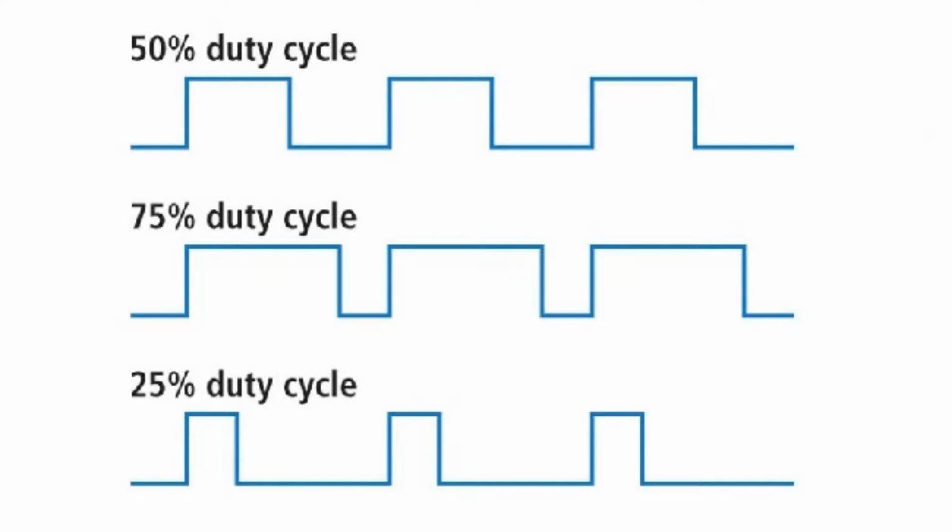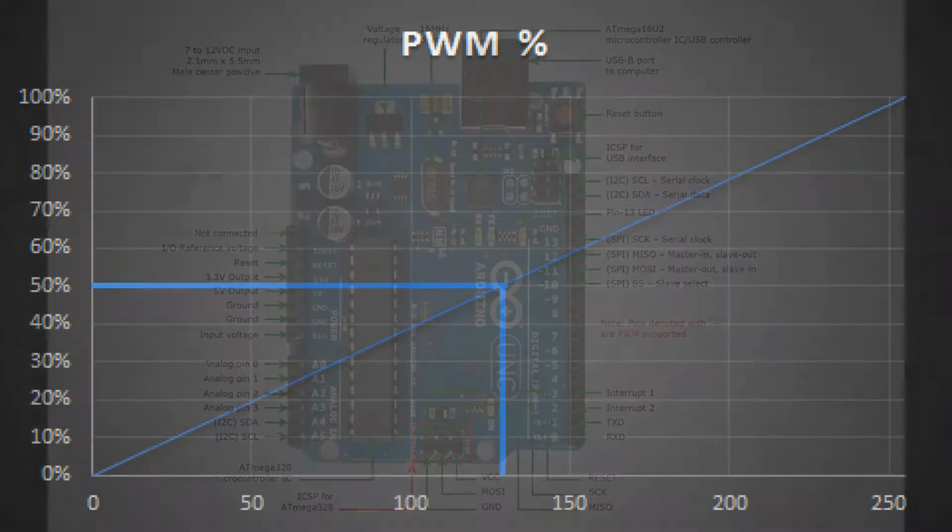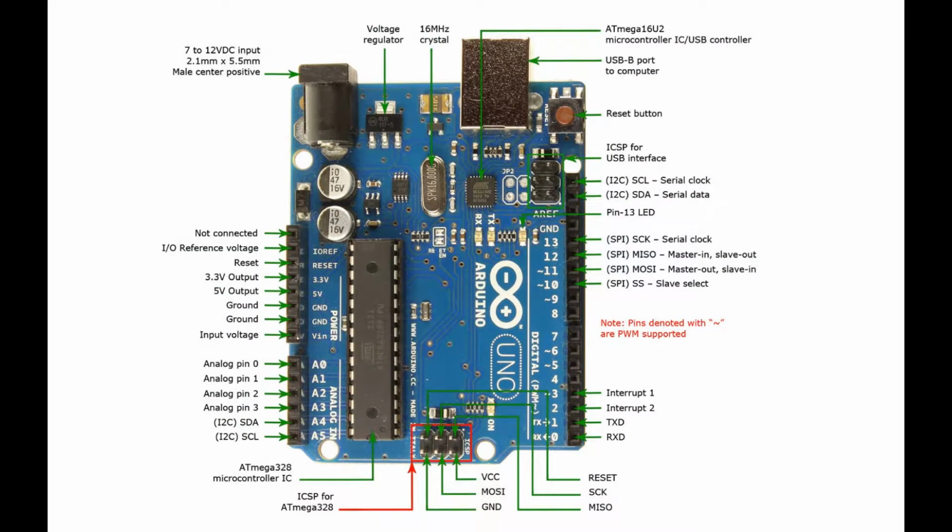A clock set at a frequency of 500 Hz, or about 2 milliseconds per interval, allows you to control the opening and closing cycles. The value varies between 0 and 255, where 0 corresponds to no current and 255 corresponds to a continuous current. For example, the value of 127 would toggle the state open and closed every 2 milliseconds for a 50% intensity. Remember that the output of the Arduino is only 5 volts, and the output power is not sufficient to power up a whole band of LEDs.